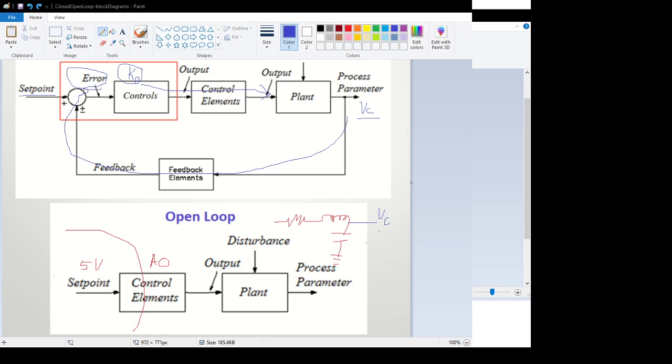And now my input, when it comes in, is an integer. The analog card is just reading in that voltage signal and converting it into an integer value, which is actually millivolts. So I'm going to convert that to a real value. Okay, so I'm going to have my voltage across my capacitor. I want that to be a real value, so I'm going to have to divide by 1,000 to make it a floating point value. My set point, I also want to be a floating point value in case I want to set it to, say, 3.75 volts or something like that.